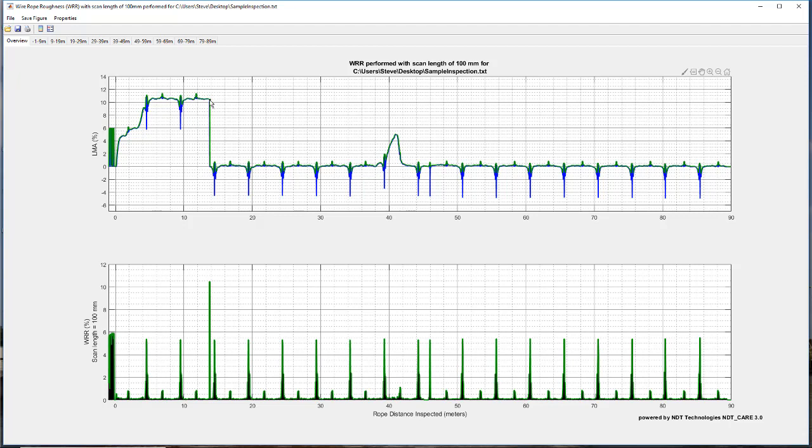So please note, if we do not do the LMA reset function here, your system will essentially go off with this remagnetization bias. To get rid of that, it is very important that you do that reset. As we're going in the inspection, at roughly the 40 meter mark, you'll see again this big spike in the LMA signal. This is the inspection artifact where the inspector brought a piece of metal nearby and created this spike in the LMA signal and then removed it here.